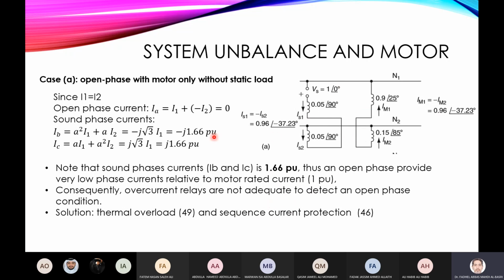We can also detect it using comparison between phases. If one phase is fully lost and the others have current, you can also use imbalance conditions. You compare the currents. If they are different by a very large amount, this is an imbalanced situation, and you can detect this also.